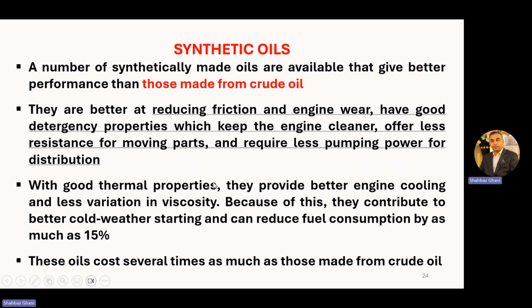With good thermal properties, synthetic oils provide better engine cooling and less variation in viscosity. Because of this, they contribute to better cold weather starting and can reduce fuel consumption by as much as 15%.